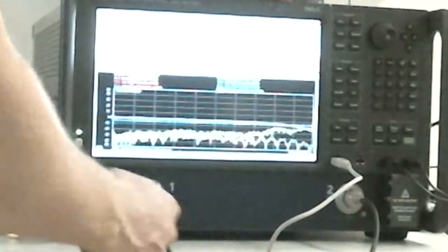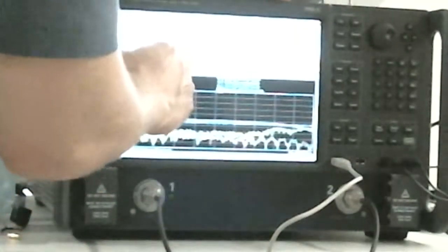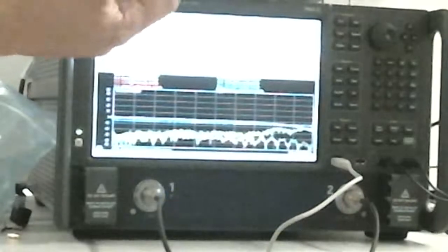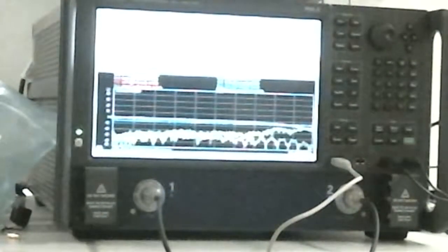So then it just says I want to connect these two. You can use an adapter. You can also use this cable. So do the measurement, and it'll give me a rough delay. You can see it says this is about 3.06 nanoseconds of electrical delay. And if you know the dielectric and the approximate length, you can say, yeah, that sounds about right, or no, that's way off.